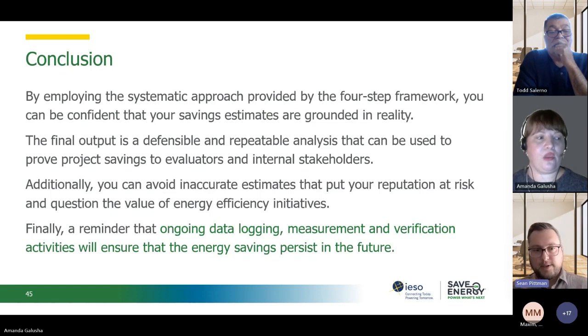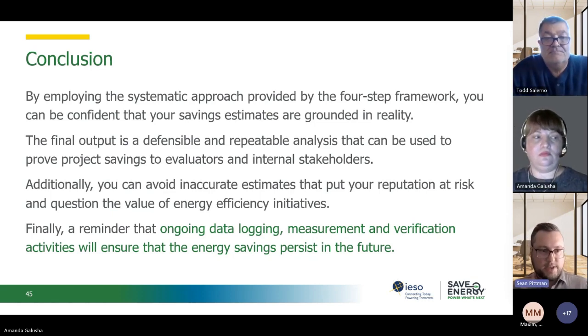A final reminder: ongoing data logging, measurement, and verification activities will ensure that energy savings persist in the future. Something that we see very often is that you don't have that follow-up and those ongoing M&V activities to monitor and observe the changes over time. You may have ongoing logging and data metering, but is anybody looking at those? Are you identifying quickly when things deviate or drift from the project outcomes or objectives? So it's very important to always keep that ongoing process of monitoring, measuring, and re-verifying to make sure that those savings persist over the long term.